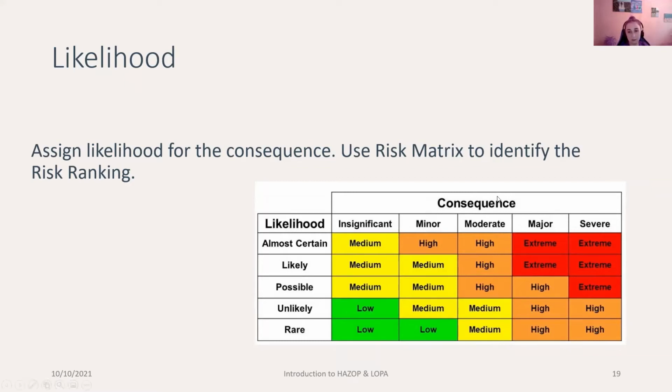And that's why you will go to the severity of this area, and afterwards, how possible this could happen, how possible that your cause will happen. Like there will be no flow because of, for example, that control valve being stuck.